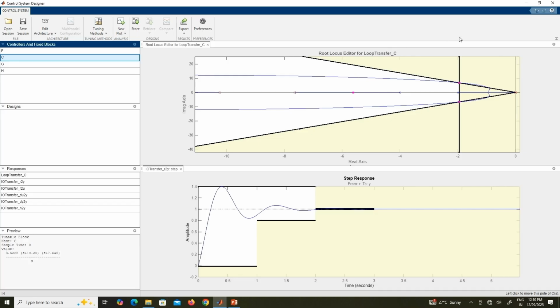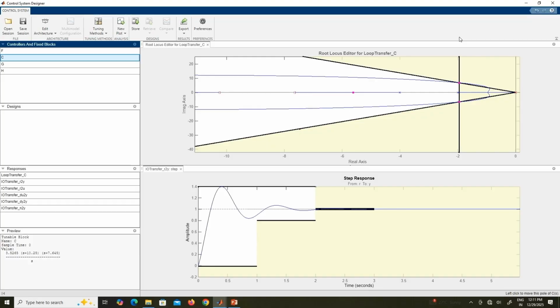Okay. Now, what I want you to do is take this transfer function and go through those entire codes where we wrote down the closed loop transfer function, and then found the step response. You will get the same step response. Right click on it and see the peak specifications. You will get what we have found out. So, in the previous lecture we fine tuned the controller from the analytical values that we came up with. In this lecture we actually did this entire thing from scratch, right.